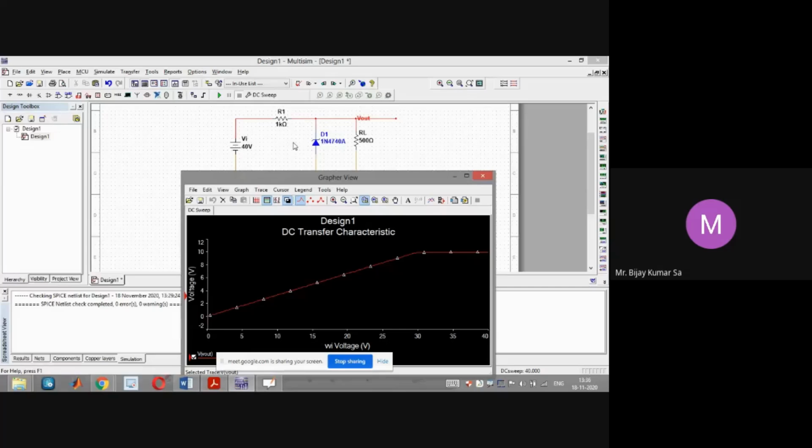So for a healthy operation of this voltage regulator, the VI must be limited below VI max, or you can say it should be ascertained that the reverse current through this zener diode be below that IZ max. Then only the entire voltage regulator circuit will be operated in a desirable manner.